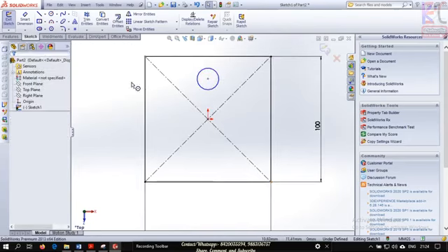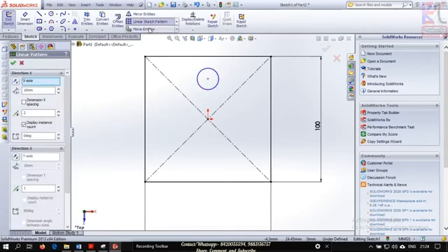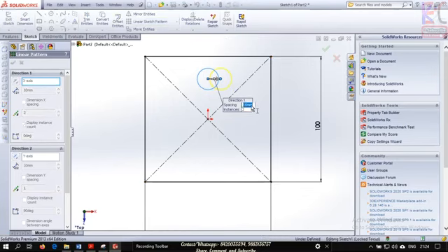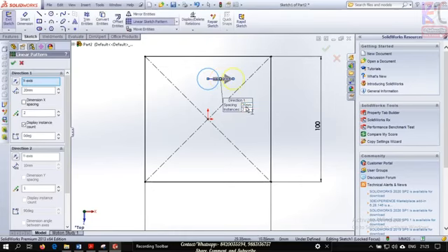One is done. Next, you need three of it. How to do this? You could use the linear pattern. Let us see, there's a linear sketch pattern where you can do this, or it's an array type of thing. Click on here. Fine. You can see a sketch is created over here. How much spacing do you want to keep for the distance? I want to keep spacing 20. Enter. How many do you want to keep? I want to keep 3.